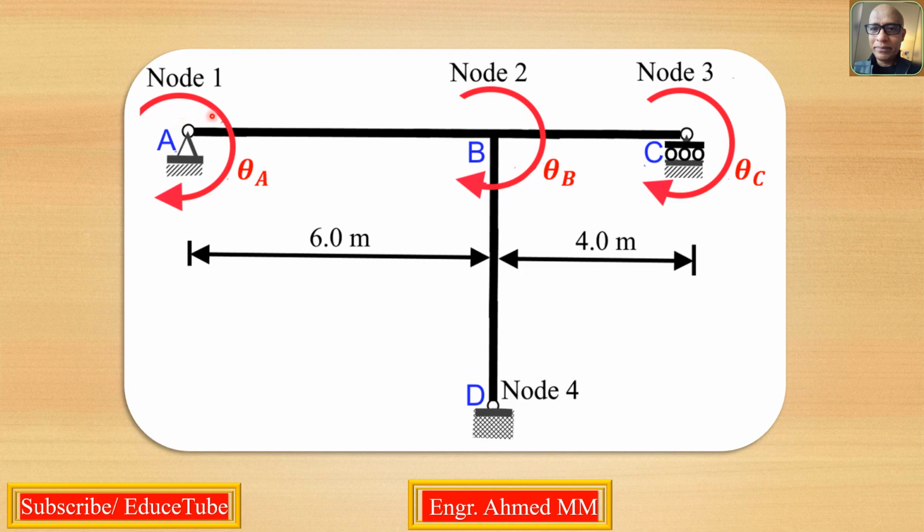The stiffness matrix for an entire structure depends on the number of structural degrees of freedom, which corresponds with these nodal or joint displacements. These three. Here, this node 4 is fixed with respect to translation and rotation. So, there are no degrees of freedom here.